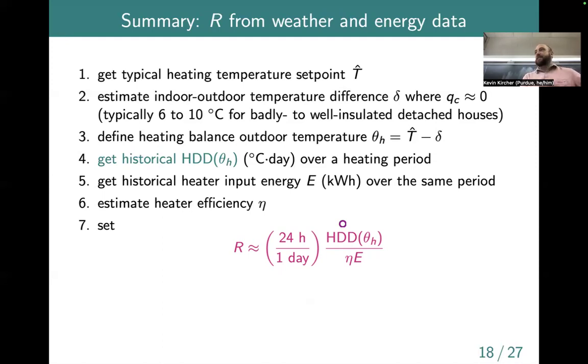And then the other units that we specified, kilowatts and kilowatt hours, require this unit conversion. But anyway, at the end of the day, we come up with an estimate of R, the thermal resistance. So now we have C, which might be on the order of 2 to 3 for a typical size US home. And then we have R, which might be on the order of 2 to 5, somewhere in that range, in units of degrees per kilowatt, again for a similar size home.